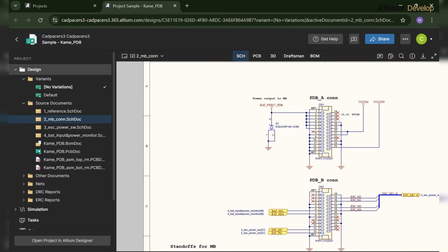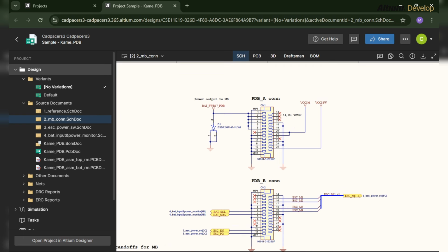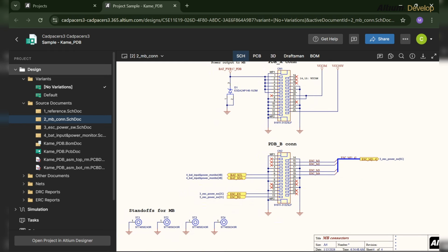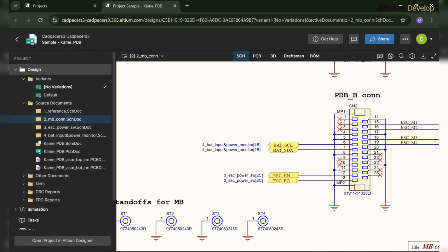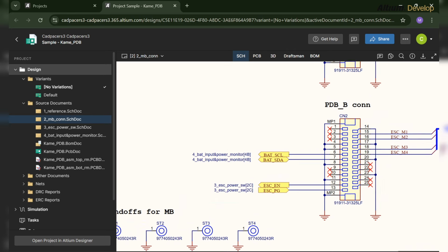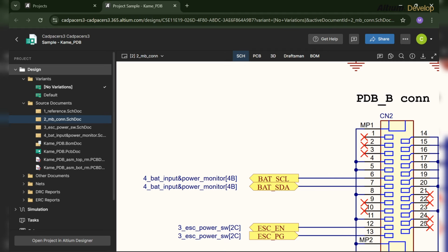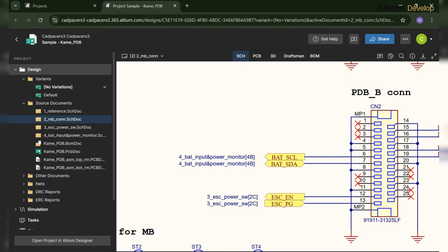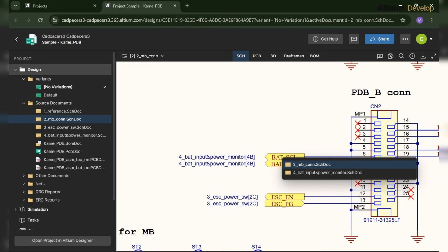Whenever some signal is coming out from the board or going out from the board, we basically use the TVS diode, because if a surge comes, it should move towards the ground. And here the studs are used for the PCB board. They are placed for mounting the board to some enclosure or somewhere.